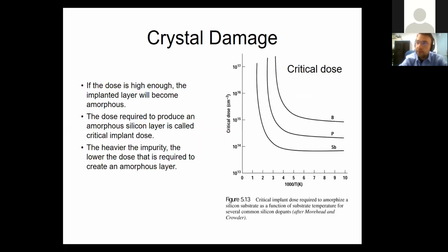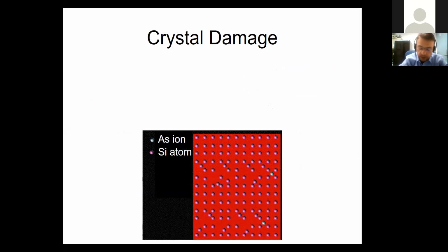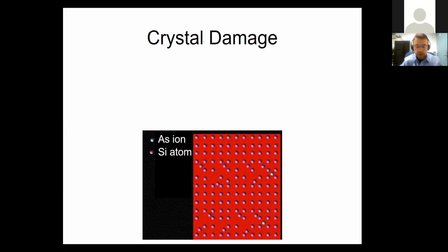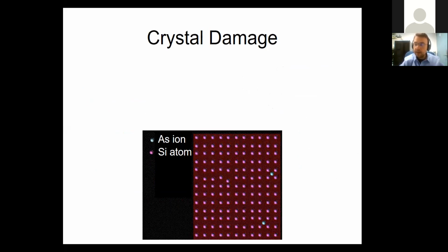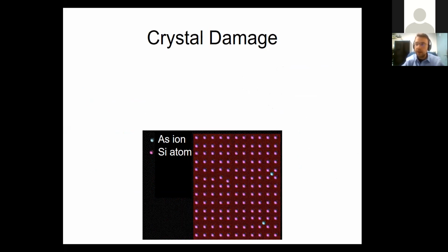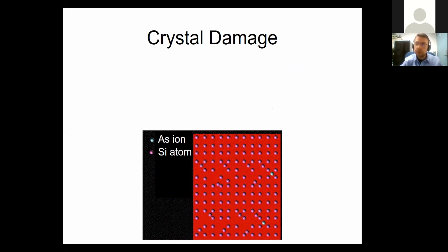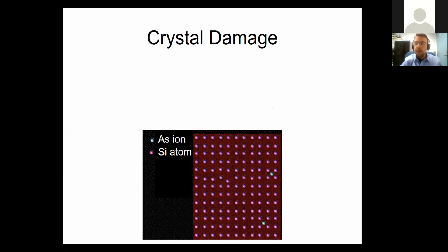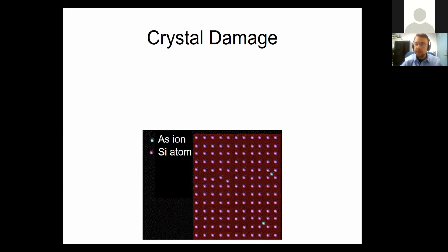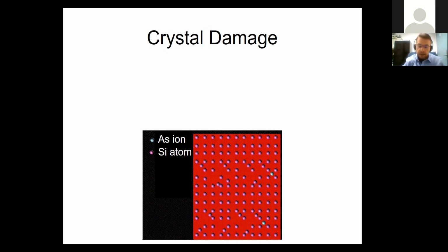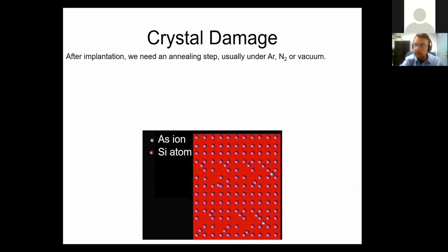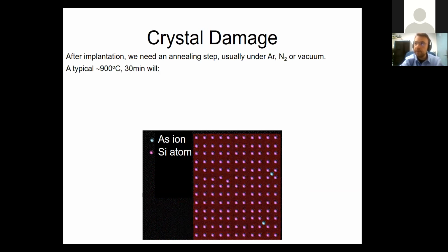So people have to come up with some damage engineering methods. How can we repair this damage? Well, the best way is, again, make use of diffusion. That's what we've seen, how the carriers wander around with the help of diffusion, but likewise, these atoms can also find their locations by heating up, or annealing, I should say, the defective crystal now.